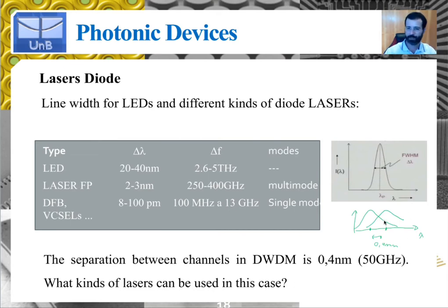So the information on this channel would have crosstalk and problems of this order. On the other hand, if we were to use narrower line width lasers, we could easily avoid this problem, because the line width of the carrier itself, not taking into account the signal, would be such that different channels do not overlap in terms of spectrum.